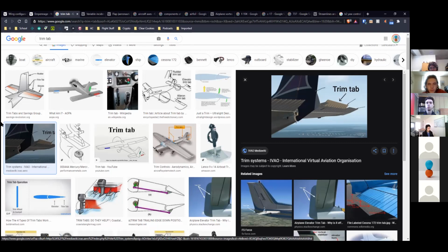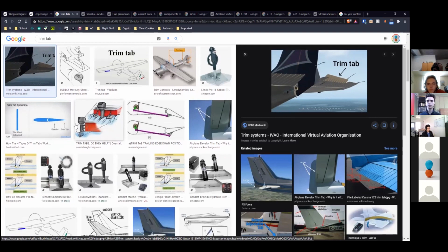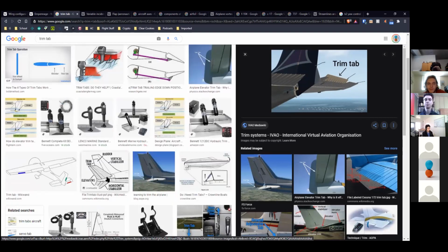So if all the controls are neutral, but you start changing the trim, then it just says change the control surface position by an amount relative to this trim amount. That way you don't have to hold the control input, but you can still get a new constant control position. Hopefully that makes sense because it was not very simple to explain.